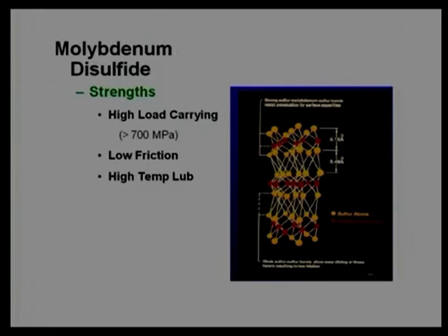One good point is that they can sustain very high temperature. This is a major reason why molybdenum disulfide is used as a lubricant in aerospace related products. They have very high temperature stability, and components made at high temperature also act as a lubricant. It is not only molybdenum disulfide that acts, molybdenum oxide will also act as a solid lubricant.